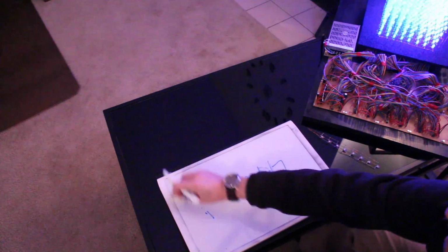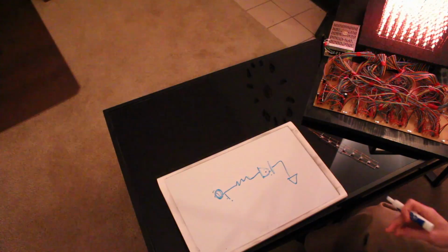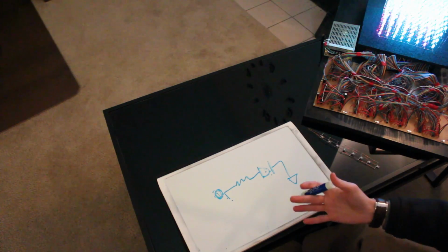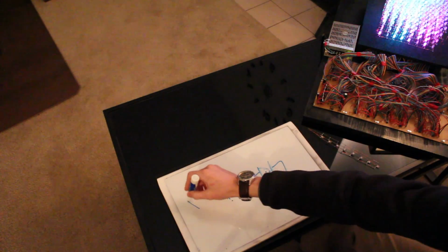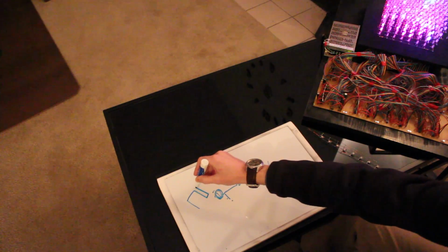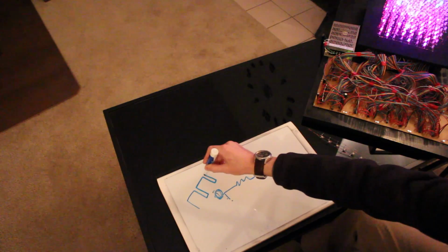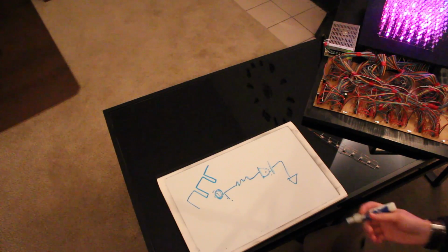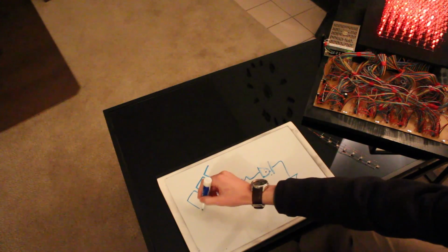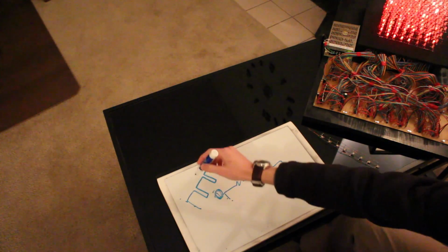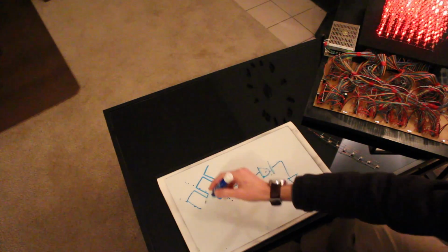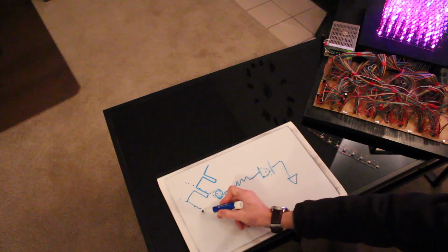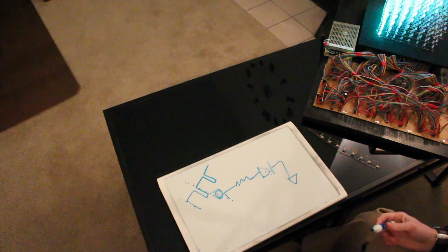So that would be something like 127 written to it. But if you increase that to something like 254, your duty cycle increases and you get a square wave that looks kind of like this at your outputs. Notice how the on time versus the off time is really increased. But that's not how duty cycle is measured. It's actually the on time versus the total time. And that's your duty cycle.